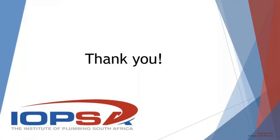It's done. So I hope that's covered about 3 or 4 often things that I find are downfalls with regards to pipe sizing, particularly pipe routing, the fact that people join it together and have multiple points into one pipe before it joins a stack. And also the stub stack, to me, is often not treated properly as a stub stack with full bore access on the top. So that's me, Sean, a couple of minutes late, but are there any questions?